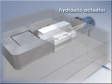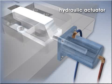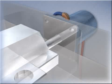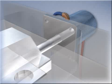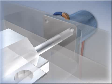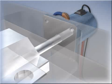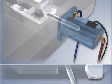Hydraulic actuators also require an auxiliary hydraulic pump, or an auxiliary function such as core pull to control the movement of the slide. Hydraulic actuators apply a greater force to the slide than pneumatic actuators. When hydraulic or pneumatic cylinders are used, it is the respective pressures that hold the slide in place during ejection. A proximity sensor located on the cylinder is used to signal the molding machine when the slide is in place.